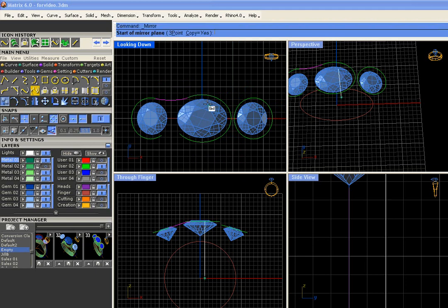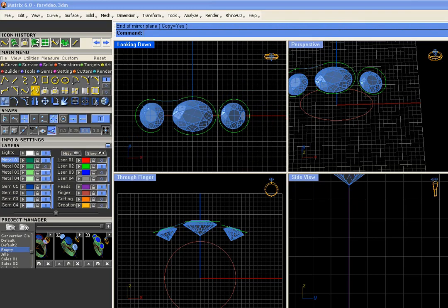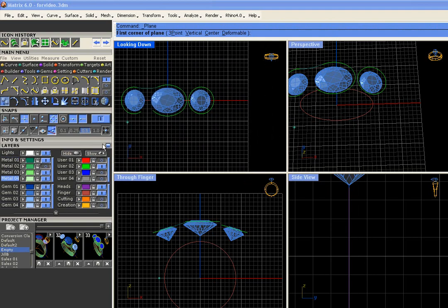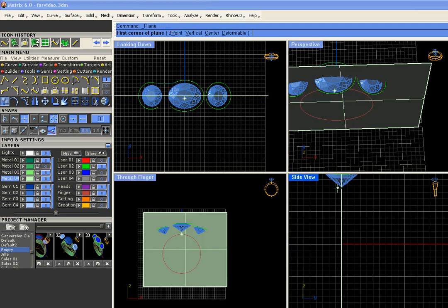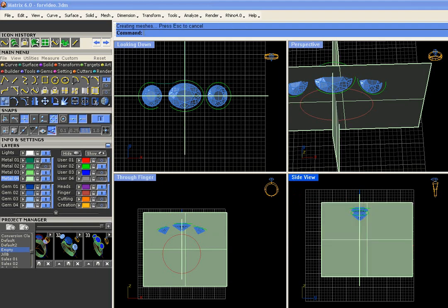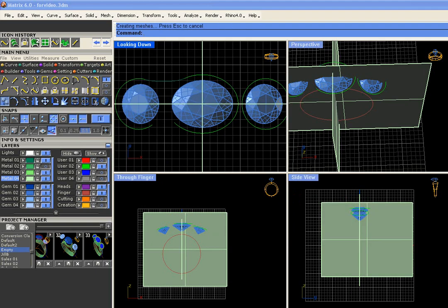We're going to mirror this to the other side. Actually, first we're going to split the whole kit and caboodle. Grab your plane command. Draw a plane down the center, and a plane down this side. We could join these three up. Join, and split with the two planes. Okay, get rid of everything that's ugly and not part of your nice little world here.